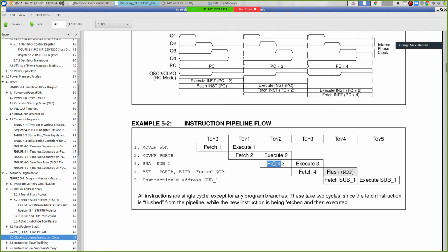And it increases our throughput so that it basically takes 4 instruction cycles to do 1 instruction, even though it takes 8, right? 4 to fetch, 4 to decode and execute. Even though it takes 8 instruction cycles to execute 1 instruction, the effect is once our pipeline is full, every 4 instruction cycles we complete another instruction. So it looks like 4 ticks per instruction. And that's the number we're going to work with when we're looking at instruction timing.